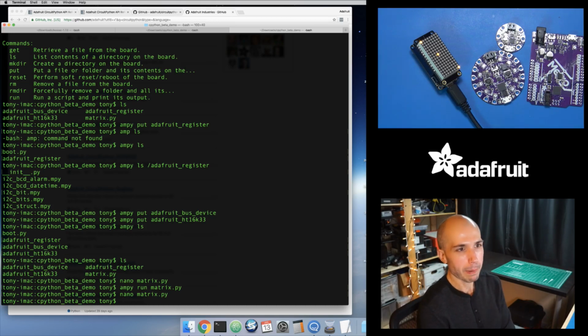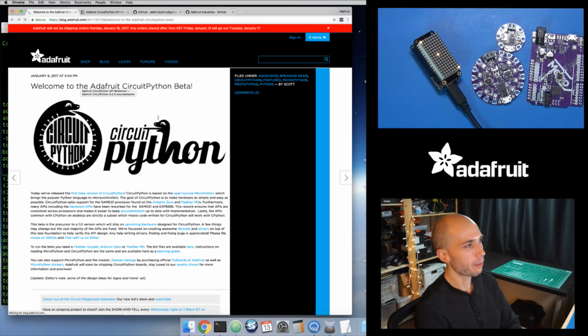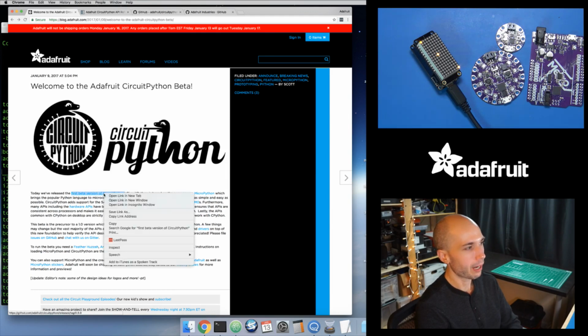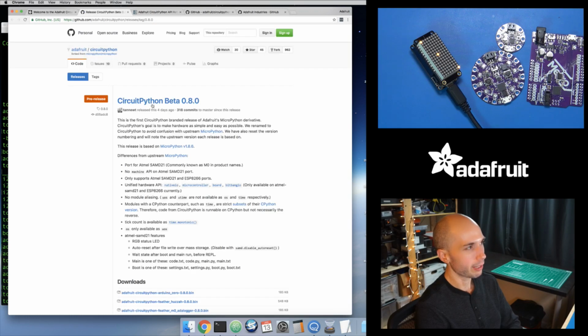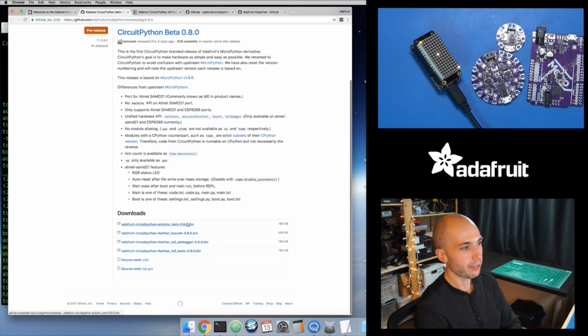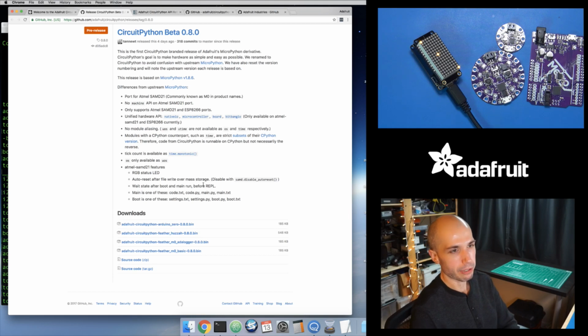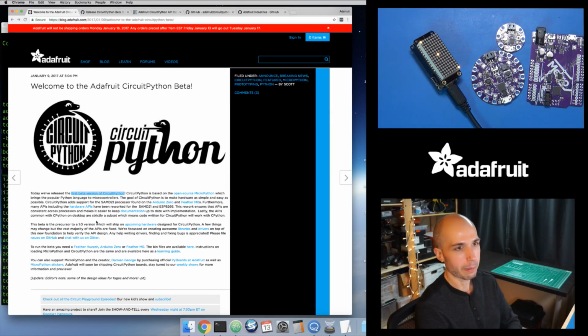So, okay, I'm going to wrap up this video then. The last thing I will mention, and I'll put links in the description when this goes up on YouTube: you're probably wondering, what now? How do I check out CircuitPython? Like I said, go back to this blog post that I'll link to, and it has links to the API documentation and the firmware, which is on our GitHub repository. You can find this under the releases of the GitHub repository. You can grab these .bin files and load them onto your board using the previous guides, using tools like esptool for the ESP8266, or BOSSA for the SAMD21. You load it on your board, and then there are links to the documentation, so you can start to play with the hardware APIs.